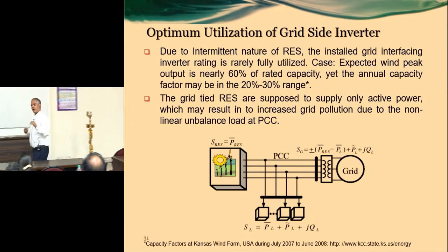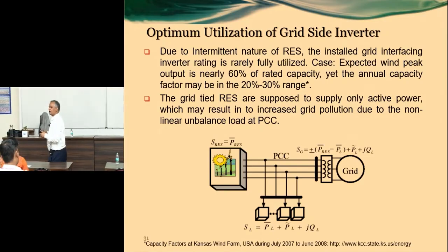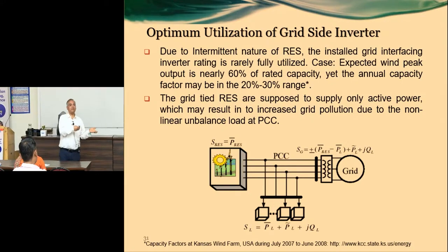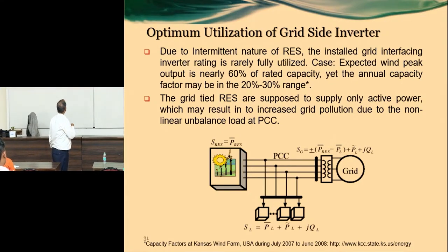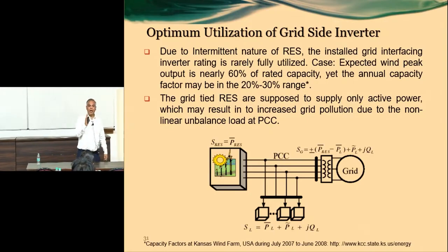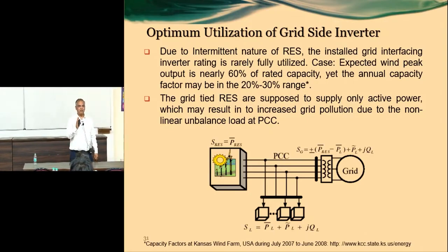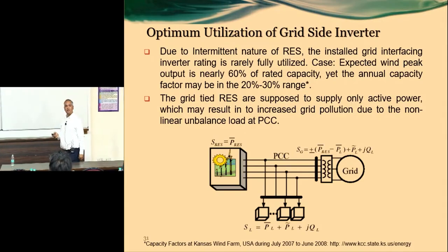So he has rightly said that all these non-linear devices, like charging, are coming up, but at the same time your power electronic device is also available there. If you combine the two, the combination of both can appear as a linear load. So only the exchange of active power: if you are generating more than the load demand, only active power is injected.